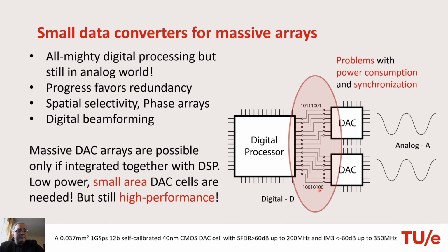At high speed, you have to use differential LVDS signaling, and you have to propagate the signal up to a certain distance. And if you use DAC chips on a PCB, large arrays of them, they occupy area, so you have to propagate these signals over a larger area.